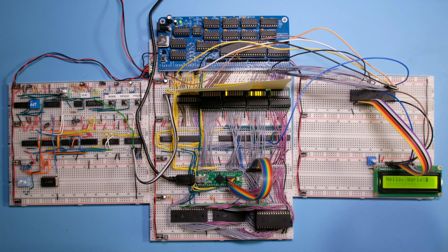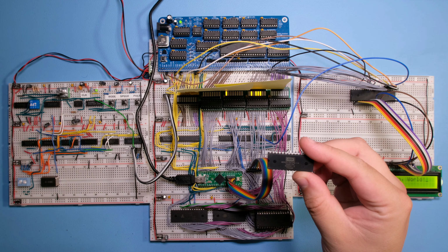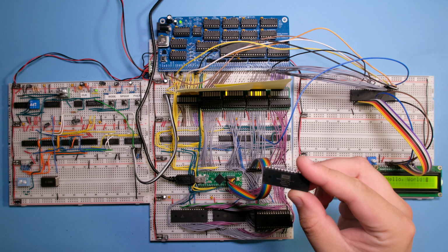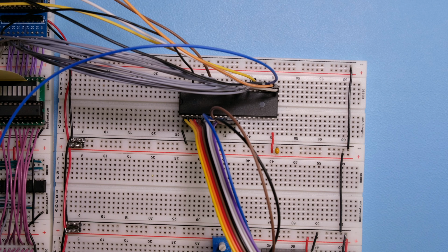Okay, so here is our computer where we left off the last time. Let's start hooking up the VIA. So the plan is I'm going to put it here on the top right, and then the space below is reserved for LEDs for the VIA, so I'm not going to use it, but I will put the oscillator for the UART over here on the side, and then I will add a breadboard on the top to connect the USB side. So let's first get started with hooking up the ACIA.